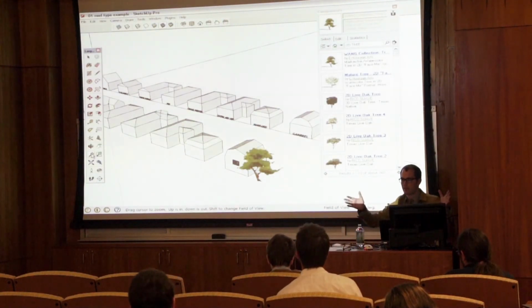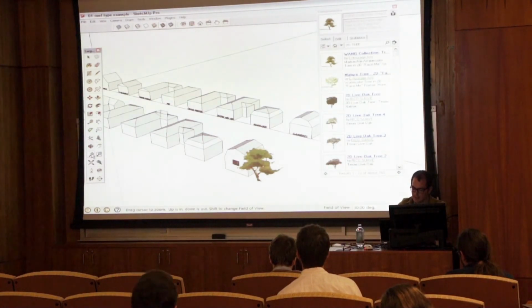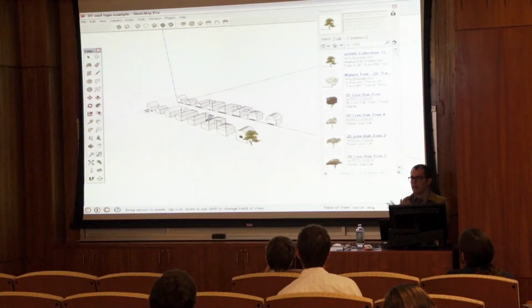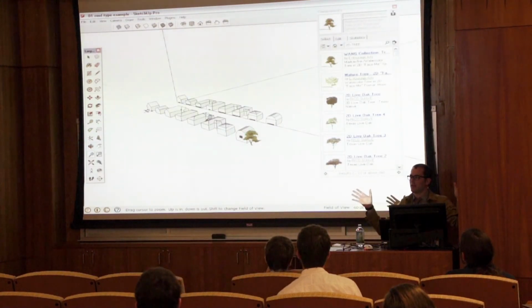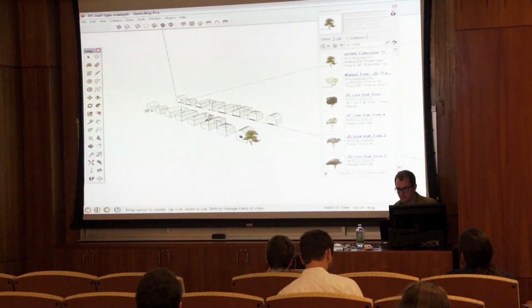That's pretty good for exterior renderings, but if you want a wider angle, what you can do is type in 60. Type in 60 and press enter, and it's going to increase your field of view. That way you can see more of your model.